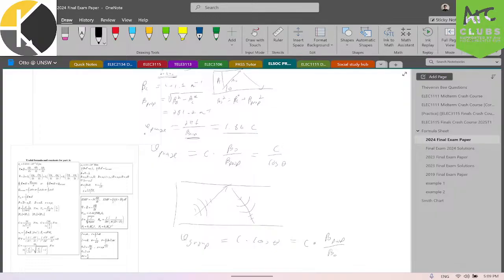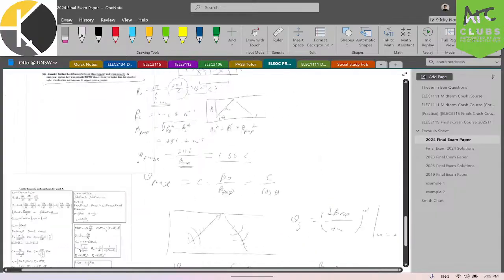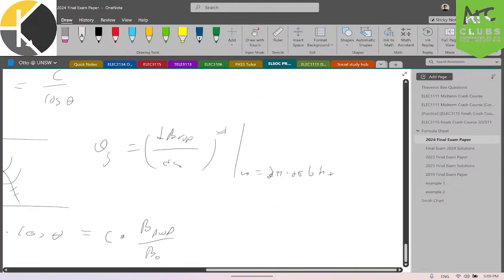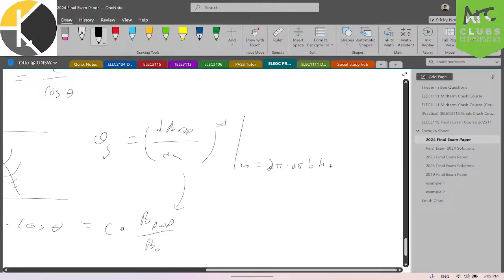The way group velocity is defined, you send some narrow band modulated signal down the waveguide and find how quickly each mode travels. Then you find that group velocity is just d omega over d beta, the inverse of d beta over d omega, evaluated at omega equal to 2 pi times 25 gigahertz. But then this will actually just boil down to this.